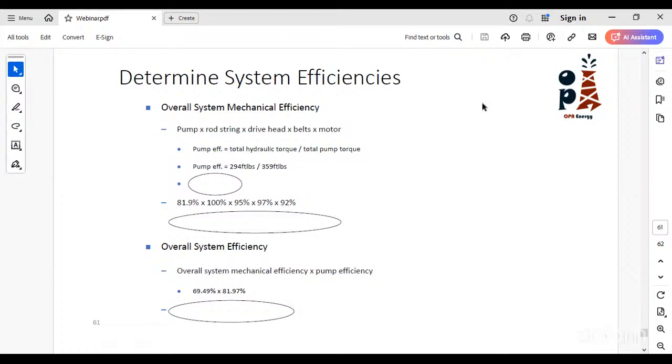So the first thing is deploying different elastomers by applying the autoclave compatibility test for many kinds of elastomers, and even metal-to-metal seal, using the rotor and the stator without any elastomer, so as not to be affected by this aromatic content or the very high temperatures coming from this application.